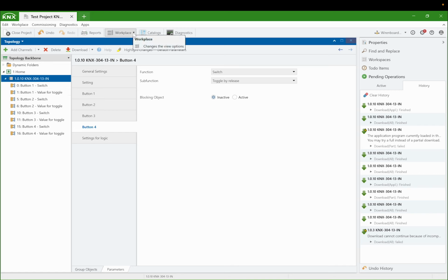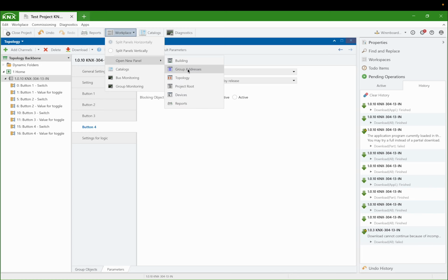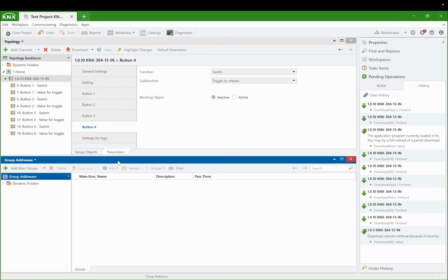Open the Group Addresses tab. By setting the group address, you define where a device sends a command when a button is pressed. At the moment, group addresses have not yet been configured. Clicking the button will not send any command. After adding group addresses in the Z-Wave Me controller, you can specify these group addresses and the controller will receive commands from the switch at these group addresses.